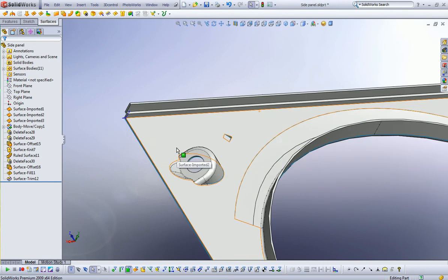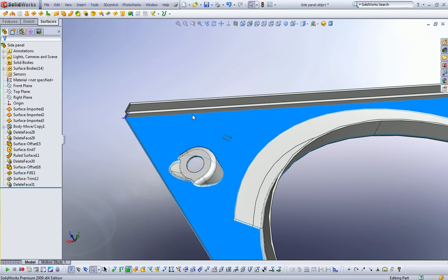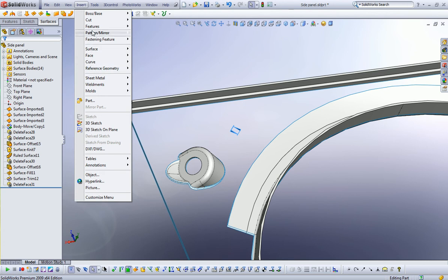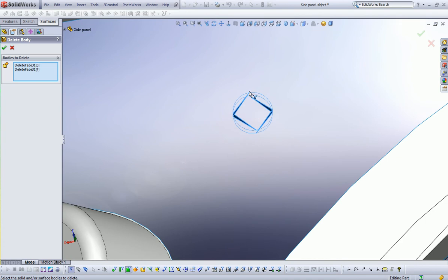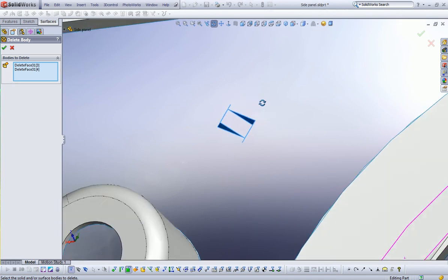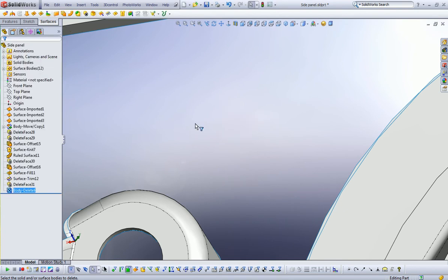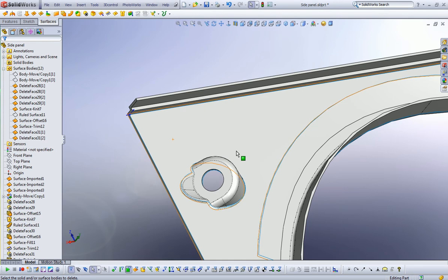To fix this, you need to delete this face. And we will hide the face we just made. So it just reveals these surfaces here. What we need to do here is remove these as a body. As you can tell, it looks like it's a circle, but when it was translated, they are still just diamond-shaped surfaces. Delete the bodies, and the holes are gone. From here, we can re-show the body we just made,